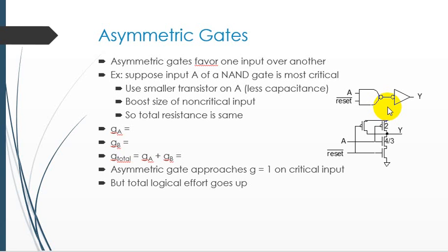This can be done with the asymmetric NAND gate that is already given here. The pull down resistance is basically R/4, and the gate still offers the same drive as a unit inverter. However, the capacitance on the input A is only 10/3. So the logical effort is 10/9. This is better than 4/3, which is nominally associated with the NAND gate. This can be very clear.